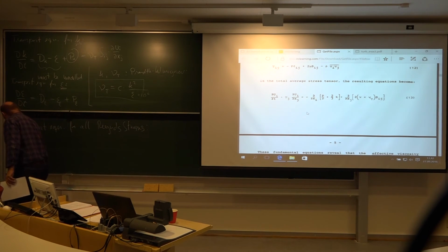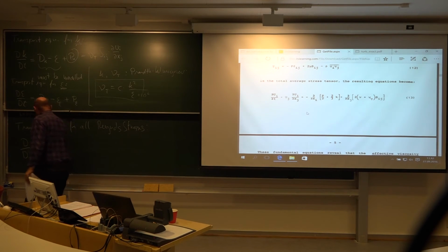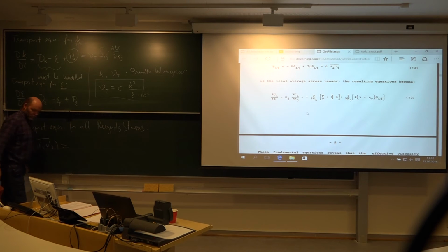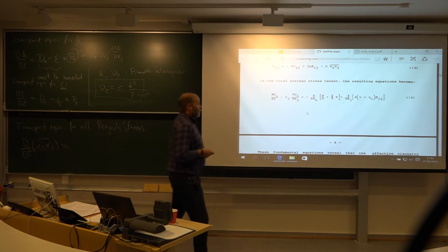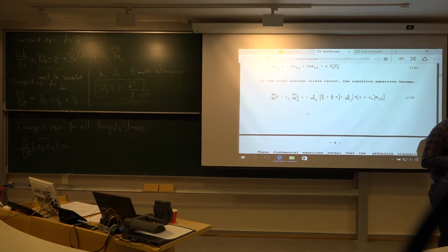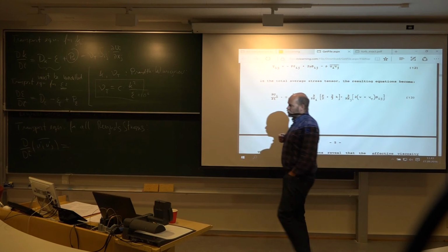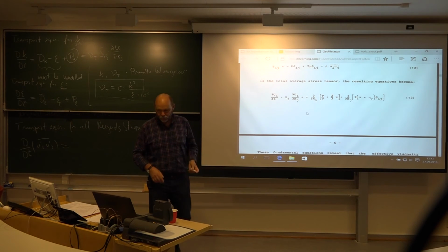So now you are talking d/dt of the time averaged u fluct i, u fluct j. And again, yes, we can go to the algebra, manipulate with Navier-Stokes, and actually find the analytically correct transport equation for any of these 6 unknown functions.